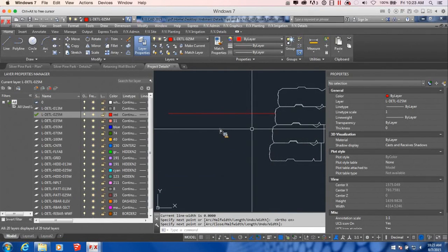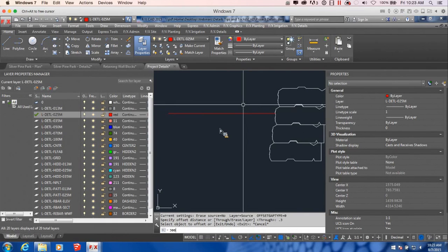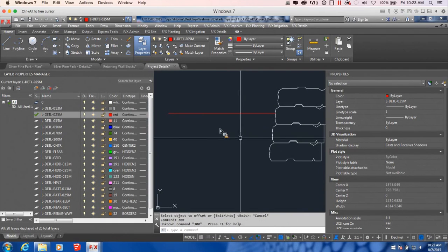And my playground, for the mulch, is going to be a mulch safety surface. So it's going to be 0.3 meter depth or a foot depth compacted. Sorry, I'm in millimeters, so that's 300.